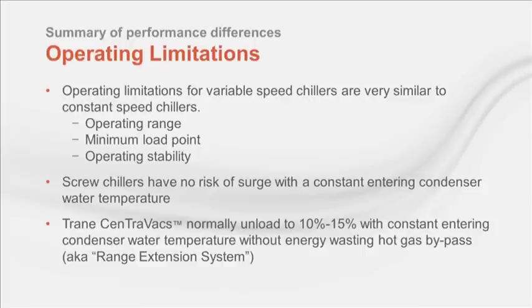Low pressure, multi-stage compressors typically unload to 10 to 15% load with constant entering condenser water temperatures without risk of surge. However, many of the high-speed single-stage centrifugal compressors cannot unload nearly that far without the benefit of significant lift relief or the application of energy-wasting hot gas bypass, something you may see marketed under the term range extension system